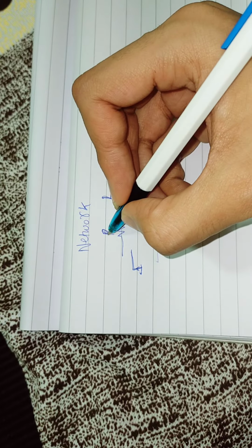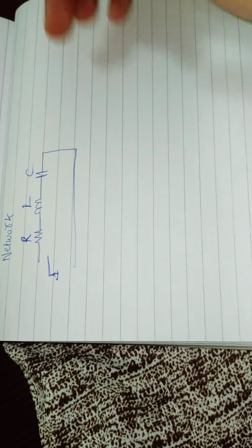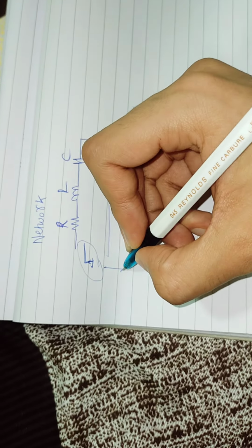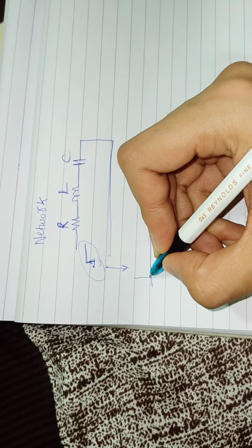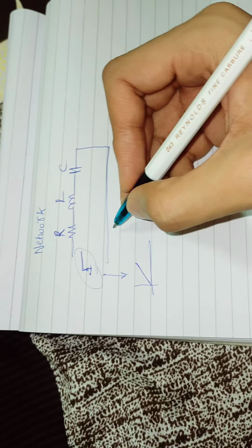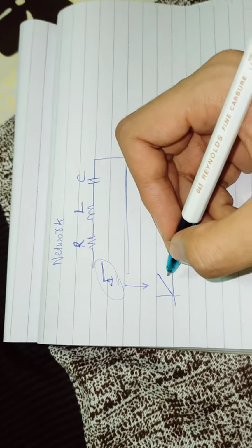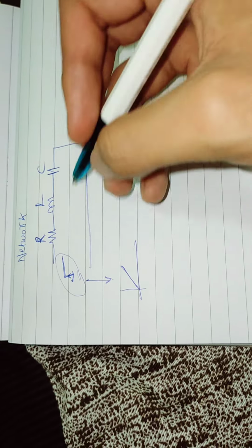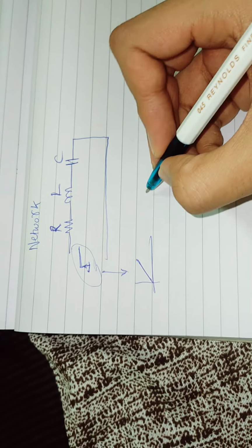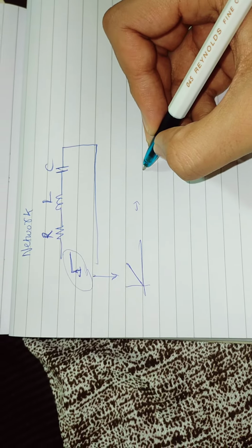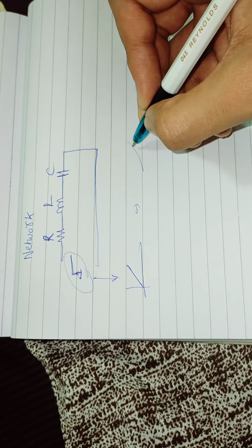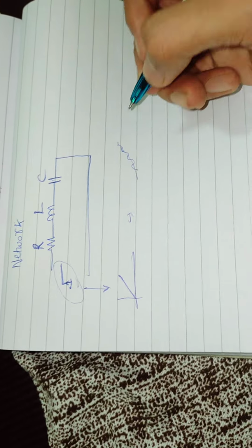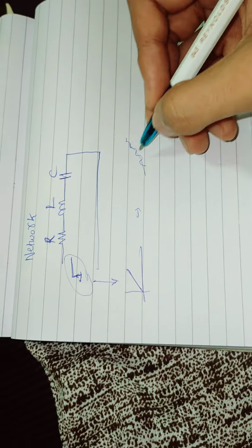But this was just the start of the question. After that, they told me to take this as a ramp input. Then I told them that this system will become unstable for a ramp input. So they wanted me to plot the time response of that unstable system. It would be somewhere increasing, with a sinusoidal variation and exponentially increasing also. They wanted to know the exact plot.